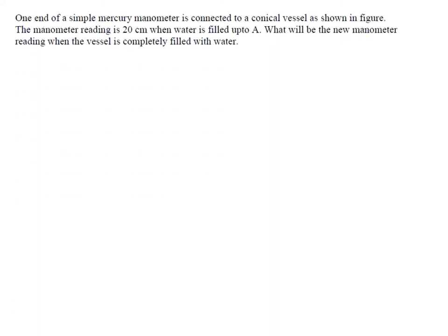So in this last problem, we have a very good problem, where we have a simple mercury manometer, where one end is connected to a conical vessel. The manometer reading is showing 20 centimeters when water is filled up to A. So what will be the new manometer reading when the vessel is completely filled with water?